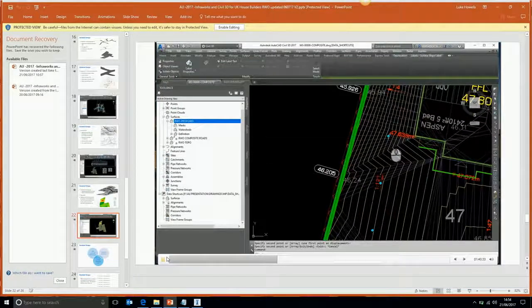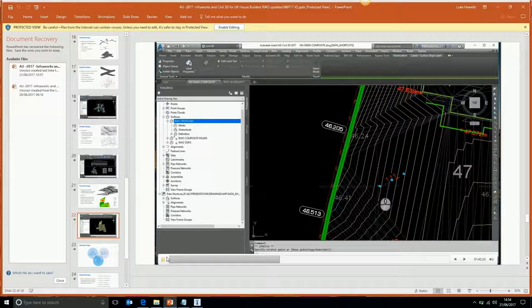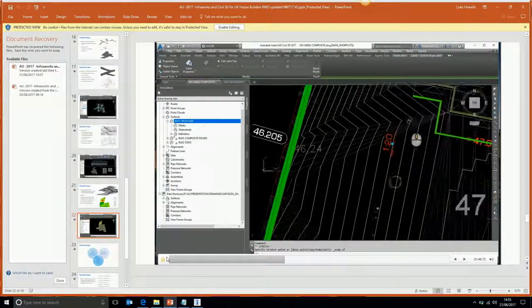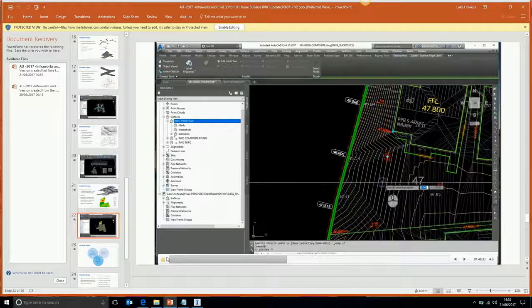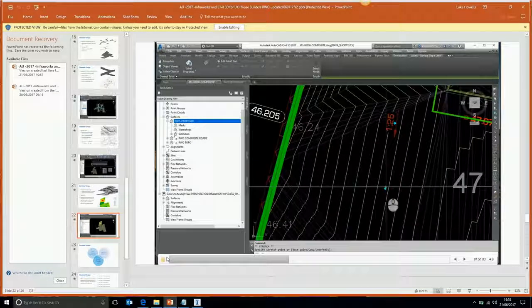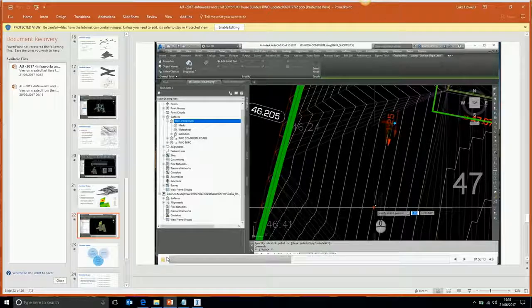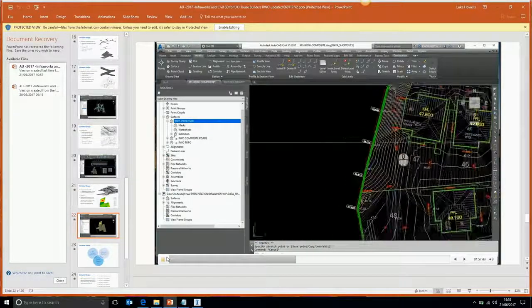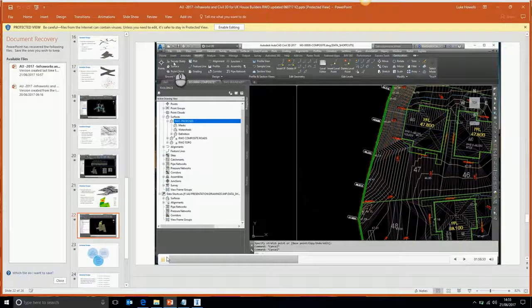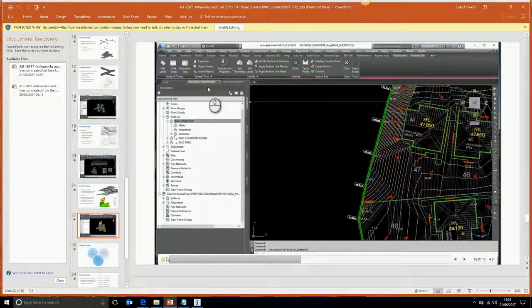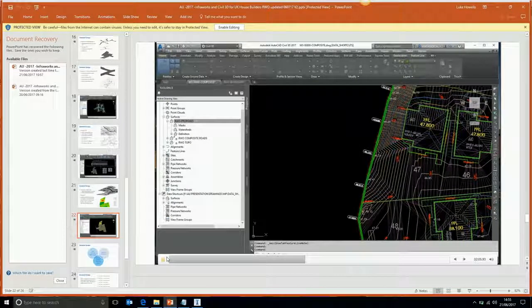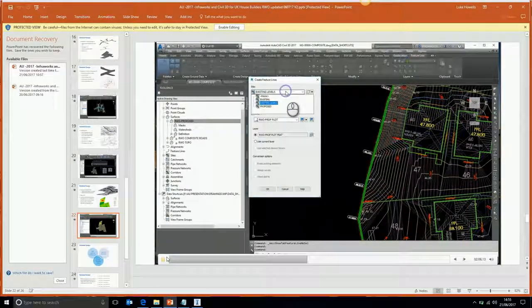One thing we're looking at here with this gradient is the fact that the back garden slopes off steeply. Developers, clients don't want to see this. We know on this development that we're happy with about a 1 in 30 gradient, I think. 1 in 25. Yeah, it's 1 in 30, so I've stretched the dynamic arrow out to that. And what I'm going to do is just show you how we'll put a simple retaining wall in the back garden, little flag on edge to remove that steep slope there.